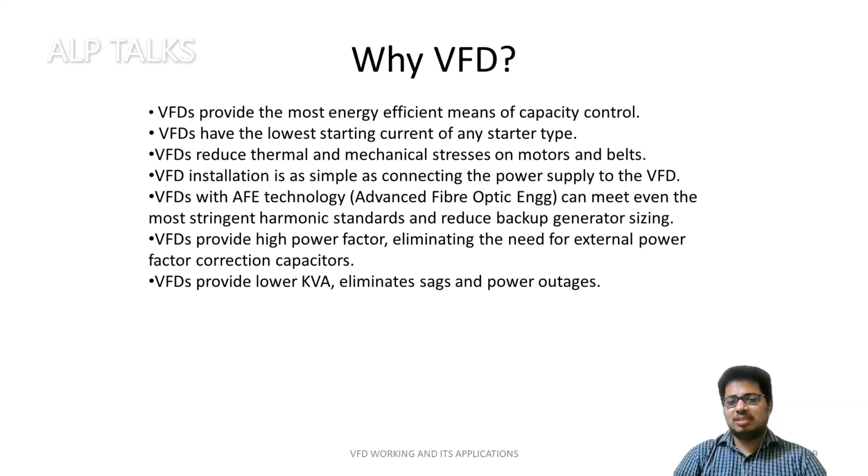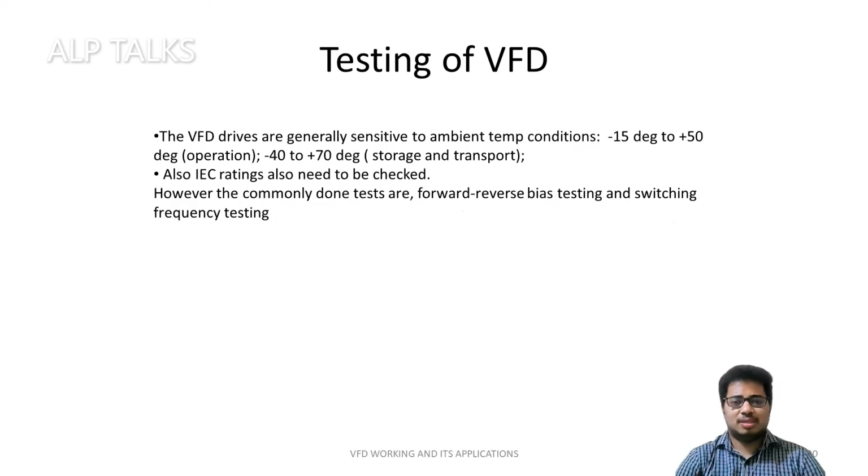VFD installation is as simple as connecting the power supply to the VFD. VFDs with the AFE, active front end, can meet even the most stringent harmonic standards and reduce backup generator sizing also. And VFDs provide high power factor, eliminating the need for external power factor correction capacitors. So VFDs provide a lower kVA, and eliminate sags and power outages.